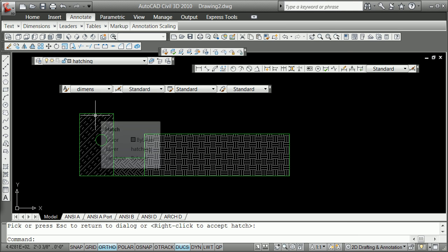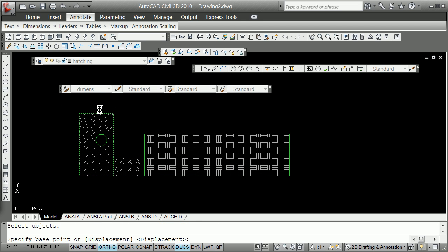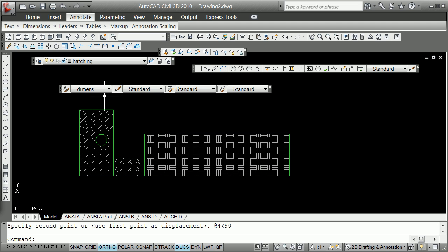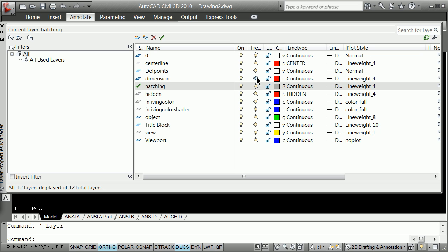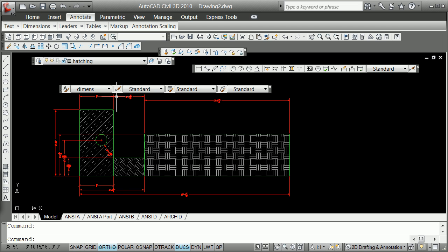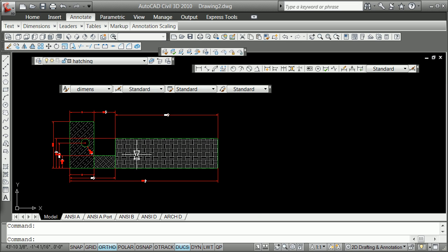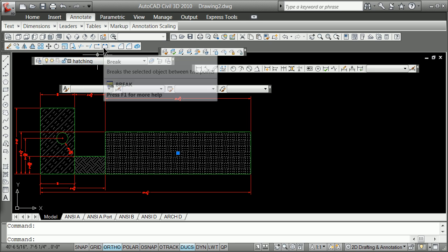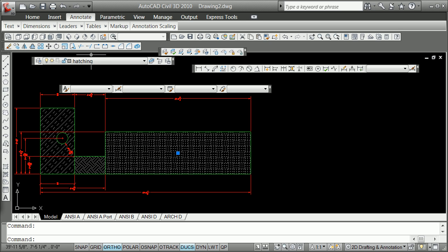But this idea, once again, is you do a stretch. That is something later you're going to see you'll do a fair bit of. If you're good, you'll use a lot of at. For instance, 4 angle 90. I'm going straight up. I just made that 4 longer. If we go ahead now and turn on our layers, we do a lot of this layer on and offing with Layer Manager. I'm not doing it here, but right now you notice how those things stretched up and went within. So, once again, putting hatches on layers that are front-end loaded or back-end loaded. So you might have something like object-hatch or view1-hatch or hatch.view1. This layering without spaces inside, so you can eventually make some sense of it.